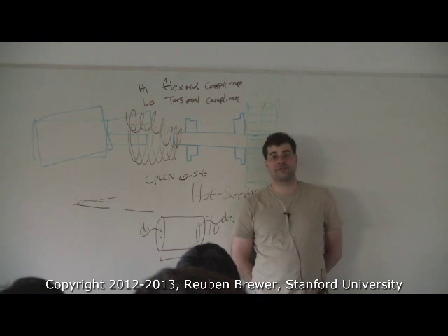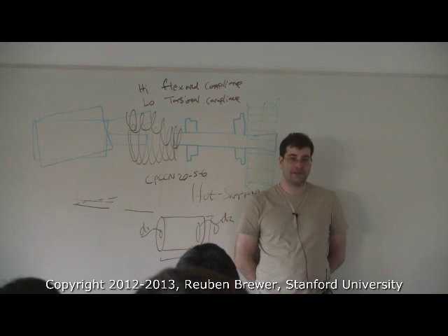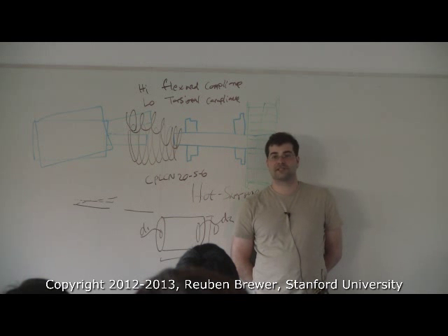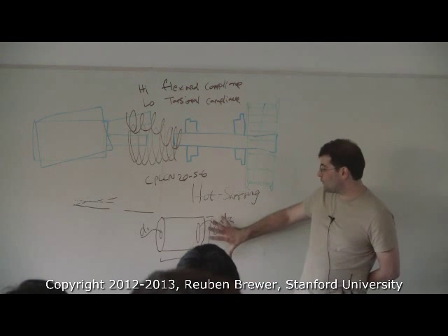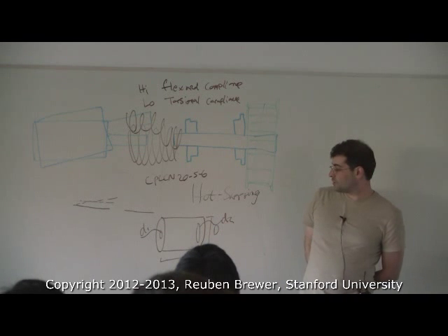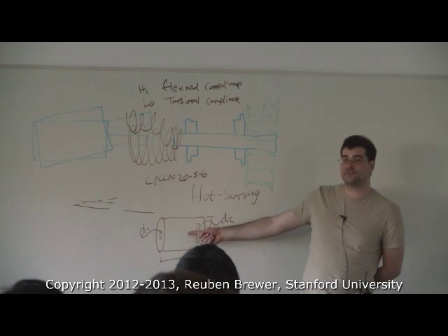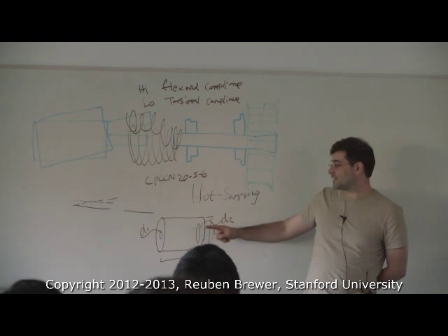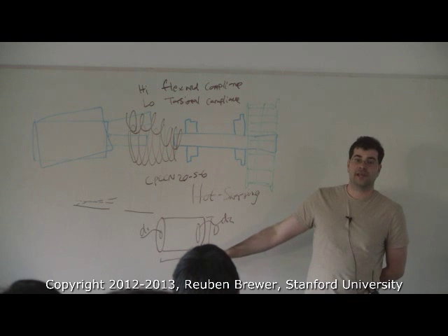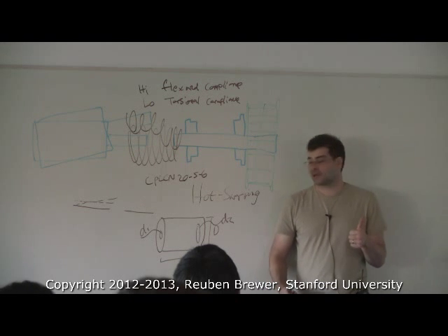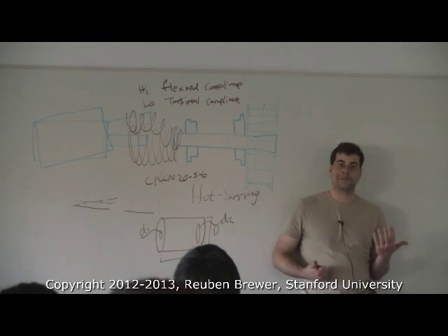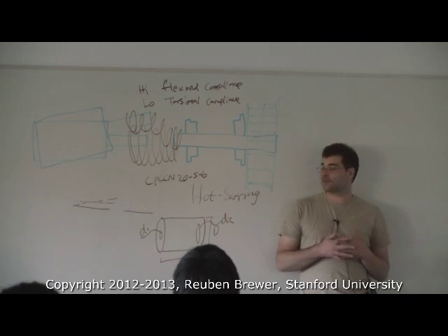The other thing is then you have to modify your shaft. However, for a given size, they have much higher torque carrying capacity than clamps. So you can have a clamp with super high torque capacity, but then it's going to be a wider diameter. So I could make a miniature version of this clamp with set screws only that has triple the torque capacity, and it's smaller. So it's sort of a trade-off, right? If you need small and huge torque capacity, you have to use a set screw. If you can get around it, try to get around it.